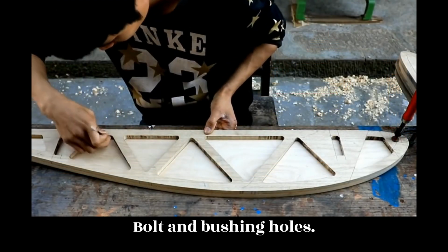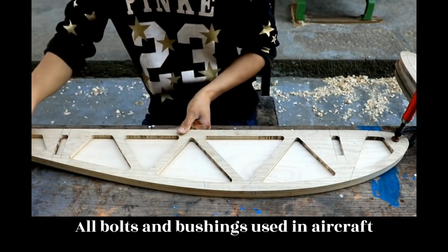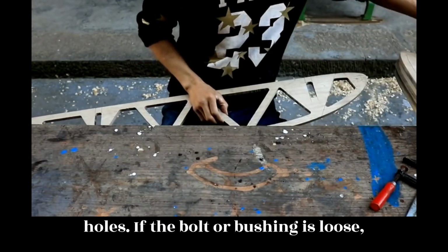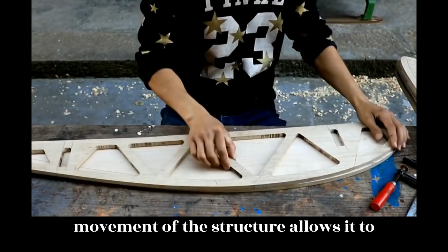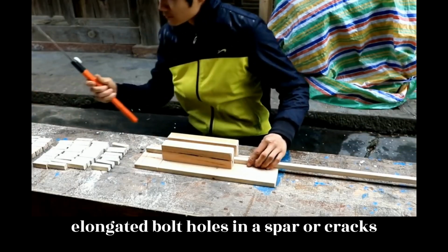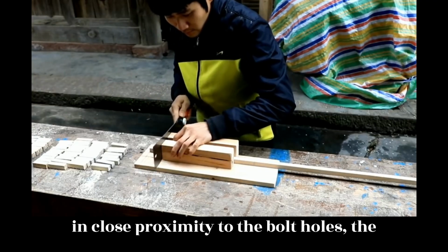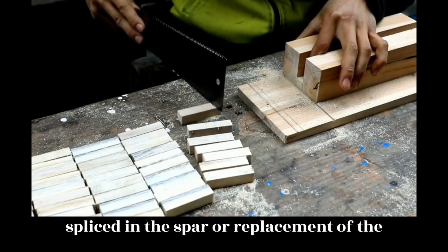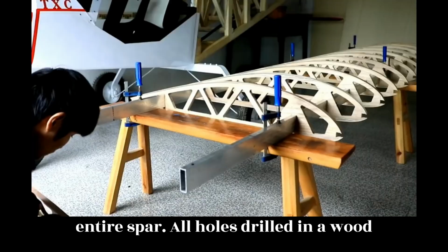Bolt and bushing holes. All bolts and bushings used in aircraft structures must fit snugly into the holes. If the bolt or bushing is loose, movement of the structure allows it to enlarge the hole. In the case of elongated bolt holes in a spar or cracks in close proximity to the bolt holes, the repair may require a new section to be spliced in the spar, or replacement of the entire spar.